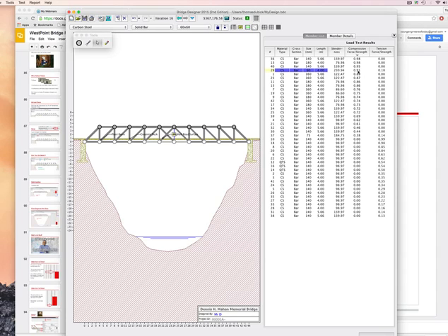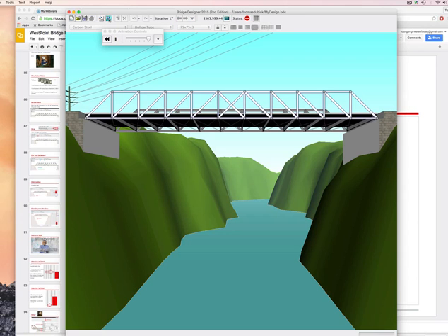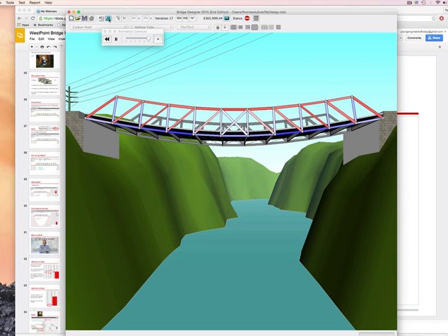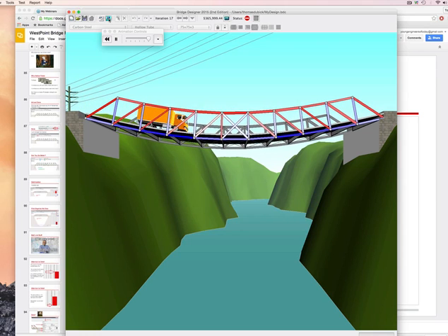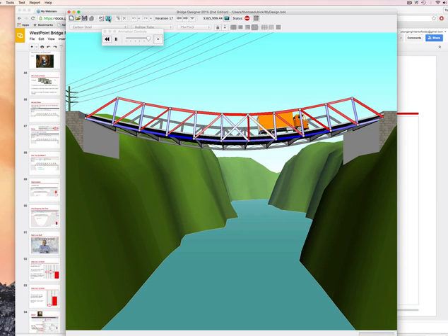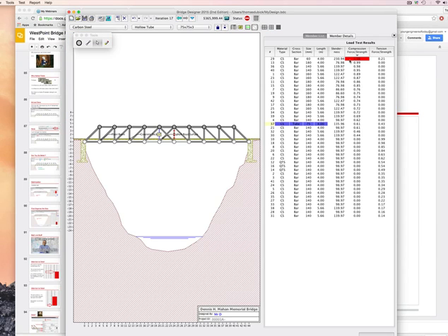Notice how it moved up here. It's now 91. So we'll go down to this one. Can I change this one? Maybe I can make it a hollow tube. Let's see if that's it. And I can look right on my calculator, see, does that save me any money? It did. Let's run it. Uh-oh. Got a failure there. See, that hollow tube, not so much. So I'm going to go back in iteration to where it wasn't failing.